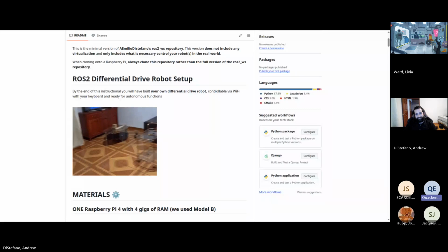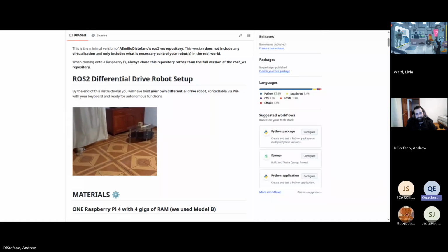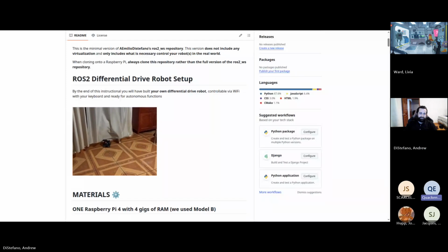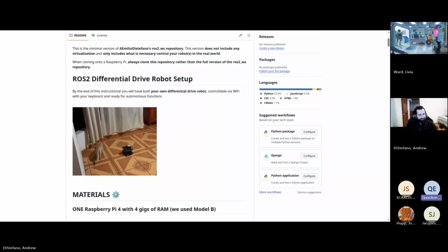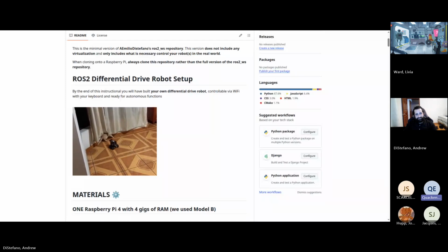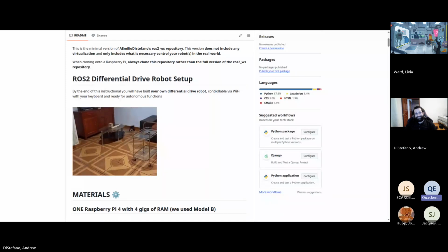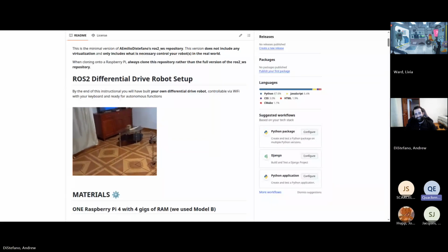So right now, we're just using a proprietary ASK (amplitude shift keying) modulated protocol that works at 433 MHz to connect a wireless sensor, like a motion sensor, to a security panel through a receiver. LoRa and Zigbee are two candidates to have a modern wireless ecosystem.